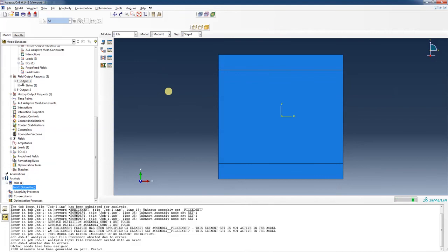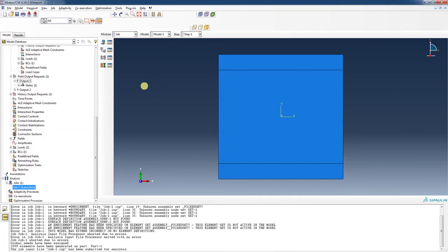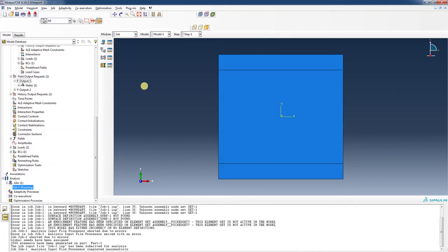And so those two loads, they're going to ramp up over time linearly from the beginning of our time step to the end of the time step. And so we'll probably not see our crack appear until we get a little bit further on in the process. So our crack initiation condition is when the tensile stress, maximum principal stress, gets to be 100 megapascals. Okay, so that's when it will start to initiate that crack.